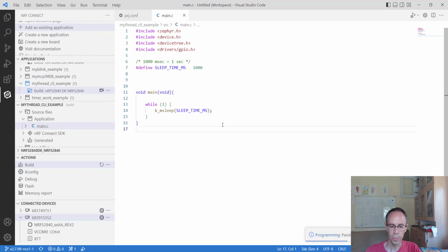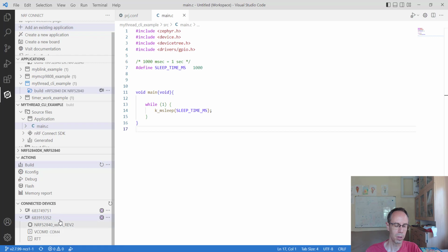And now here is also a terminal window. We have to communicate with the shell via the UART. But I don't use the virtual COM port terminal here now, because we can only use one at the same time, at least I didn't find out how to make it different. So for this I'm using PuTTY.